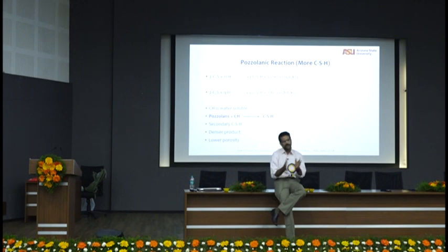So if you have ASR, in the US, plenty of ASR. The United States being a newer continent than India, things haven't stabilized to the level that the Indian subcontinent and the Eurasian plate have. So you have much more reactive aggregates there, and so fly ash becomes a very, very useful thing to control alkali silica reaction, provided your alkali content in fly ash is low. So that's a question to ask.